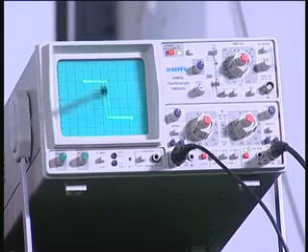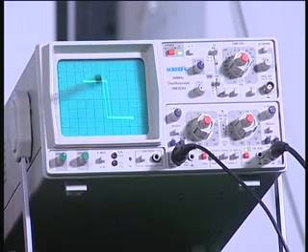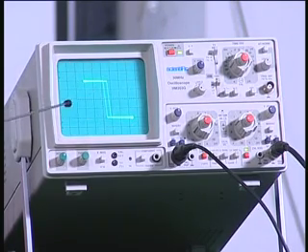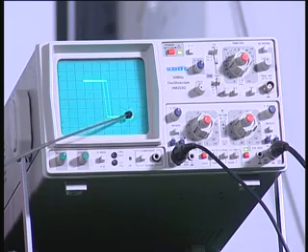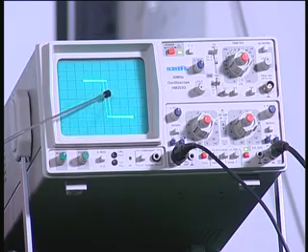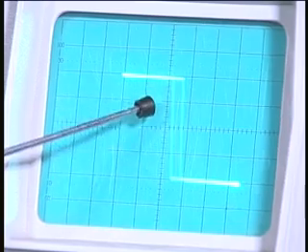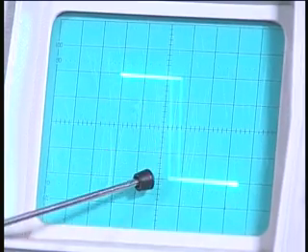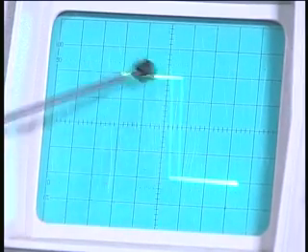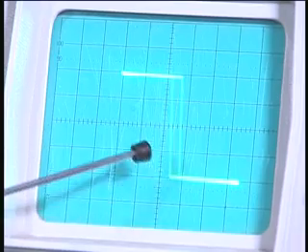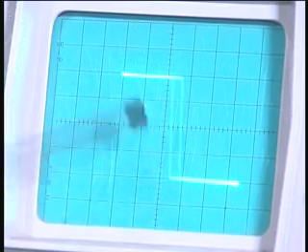I did not explain to you about 2 lines. Why do you get 2 lines here? It is very simple to understand, because when I come from here, the moment I cross this 120 microvolts, it will go to the other end, and when I come from below, it is minus 120 microvolt at which I will make the transition, and therefore these 2 lines correspond to the 2 limits of that.